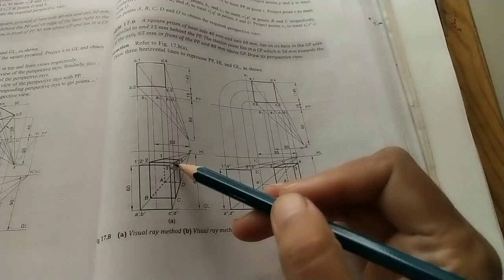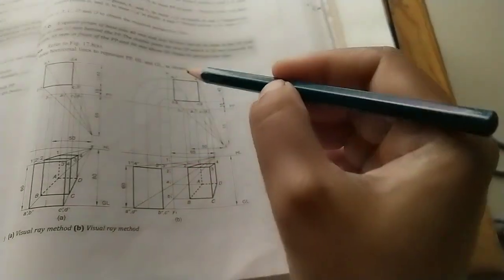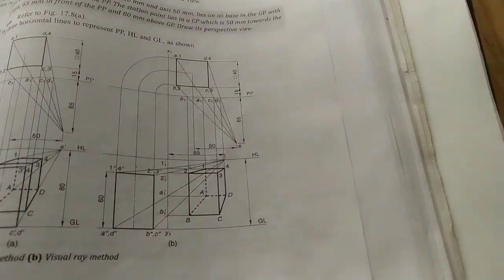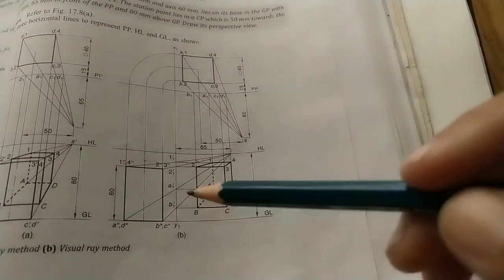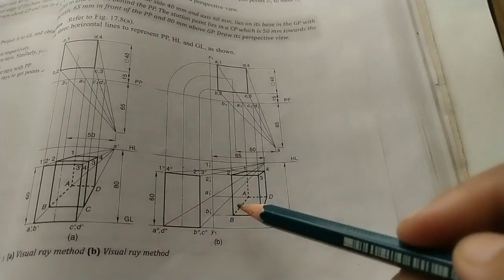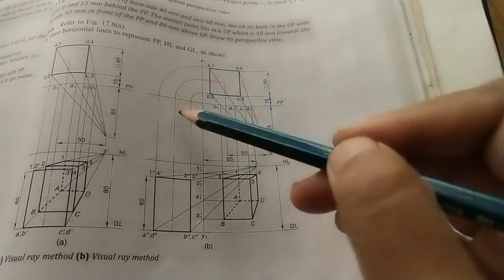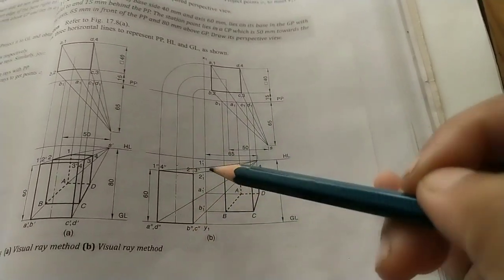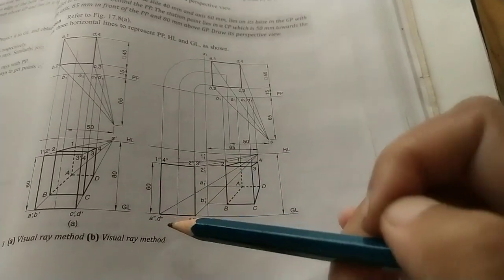If you are taking some other examples also in this question, this is the perspective projection and this bigger box is the side view. We did this side view separately here. By taking the reference line, XY line, we did the top view here, front view here, and the side view. This is the top view, this is the perspective view, this is the side view. The side view we did as a separate diagram, by taking the projection lines and transferring these projection points and doing the vertical lines. From here also, doing the projector lines from all points, joining these points to the station point and extending these lines up to the required points.